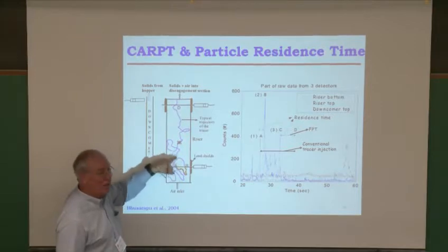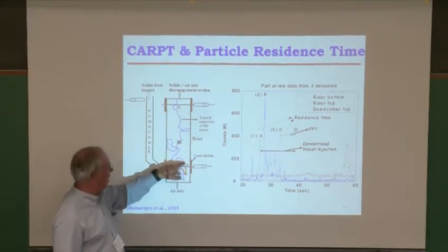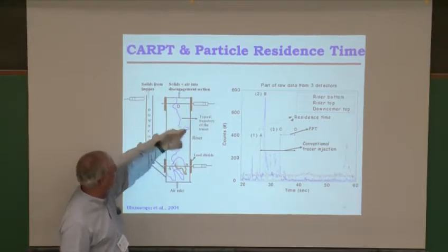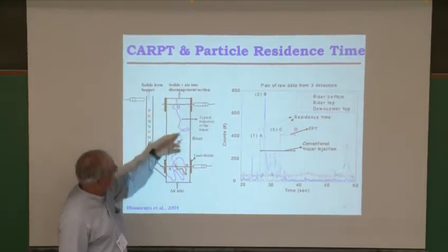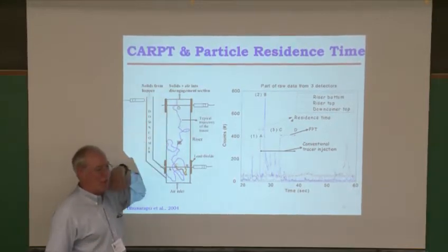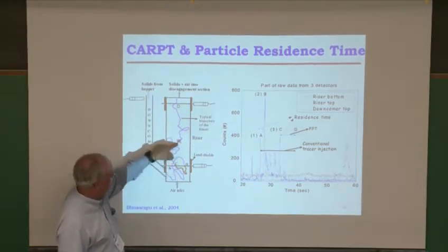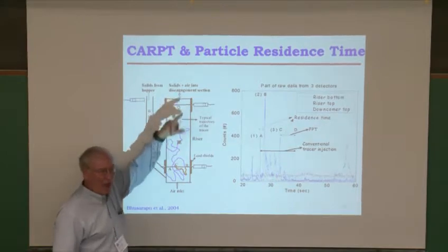So if it just spun around there, like a helical path. Well, you see here how the particle behaved during this time. It eventually made its way out, but it obviously was not flowing like we often think and say, quasi plug flow or actually dispersed flow. So this is a trajectory length, wherever that length is, how long it traveled.